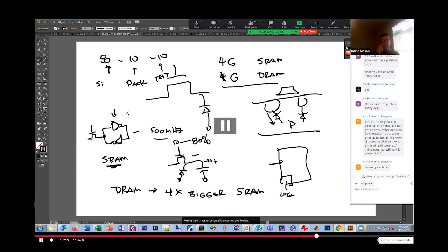It's got like 5 transistors, and basically a simple latch is an SRAM, but in the SRAM, it's built so that you minimize the area of the cell, and you multiplex them so you can read out different cells on one pin. Like normally there's a whole bunch of these connected together, right? So you just read them out on one pin. But that's an SRAM cell. And one thing to note about this SRAM is that, as long as the power is applied to these inverters, it will remember what it is. But the minute you remove the power supply, it loses its memory. So we call that volatile.